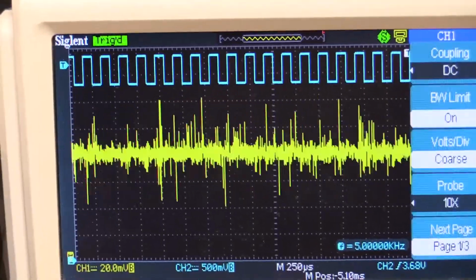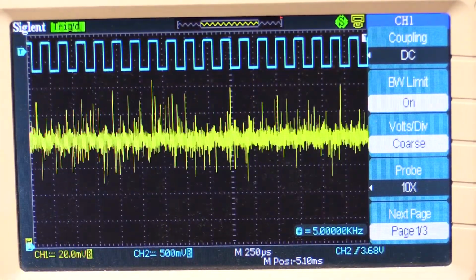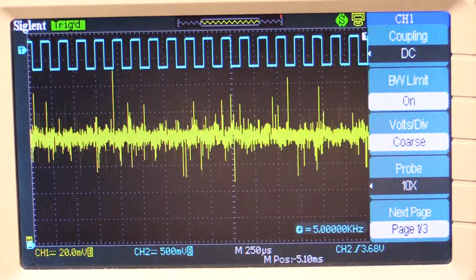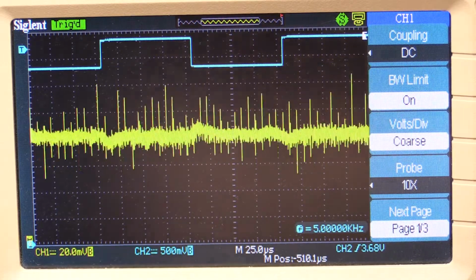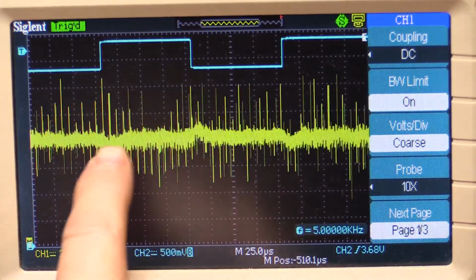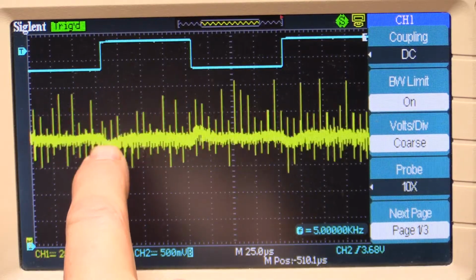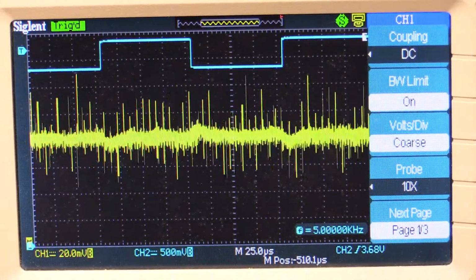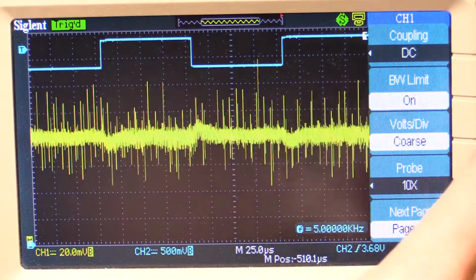And the oscilloscope is still showing us that we have no appreciable noise being added into this. You can actually see a correlation now, just that there is about, and this is purely guessing, maybe a 10 millivolt dip in the output if we ignore any of the superfluous noise that we've got there.